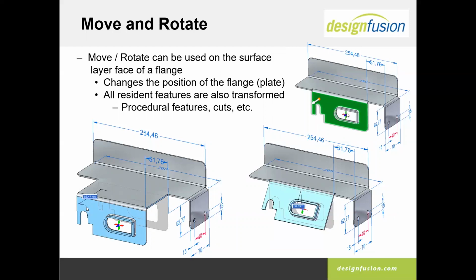Also notice that the feature, in this case a drawn cutout that resides on this tab, also moves with it because of the feature origin. And so it knows that its feature origin is this face. So if you move this face, it's got to move with it.